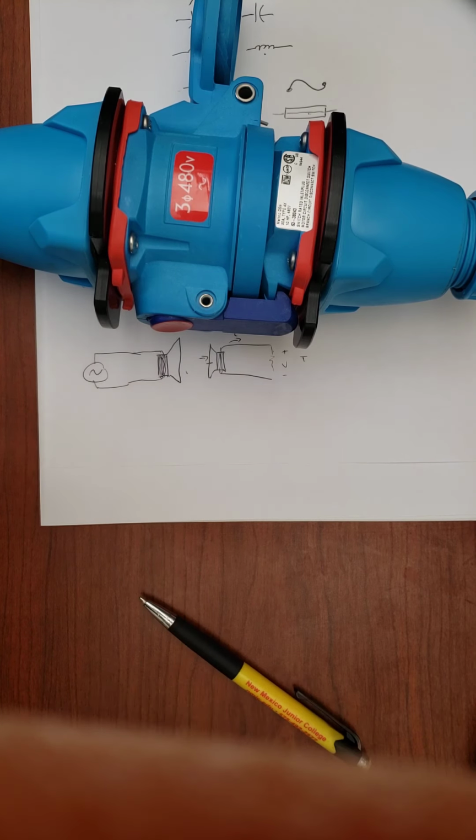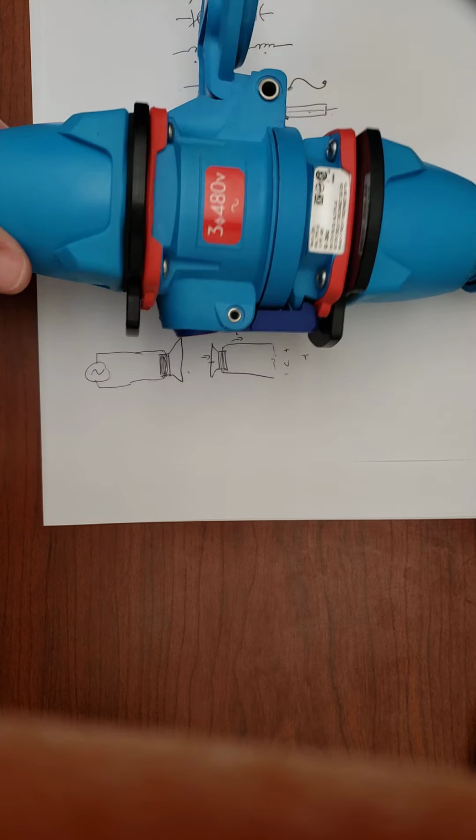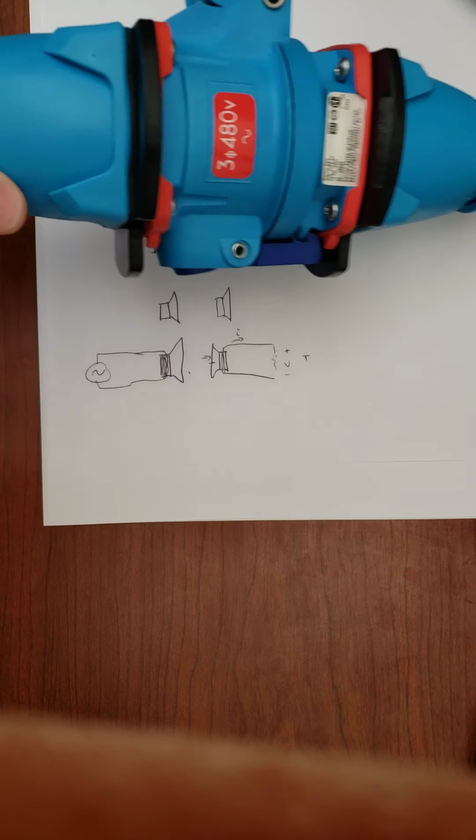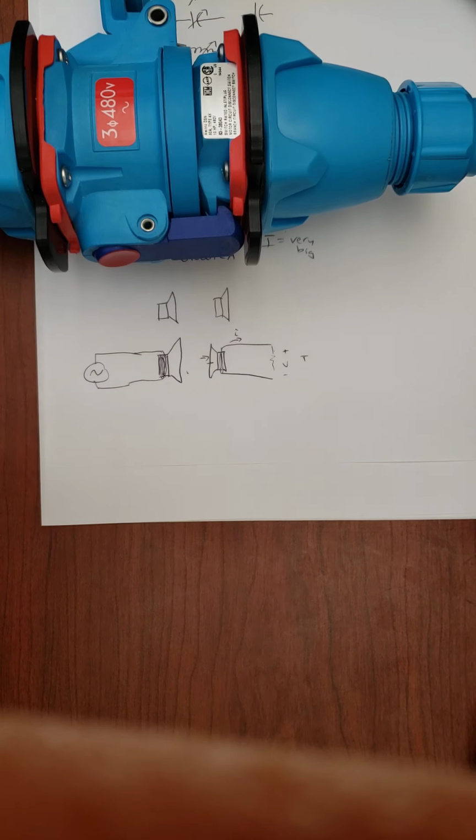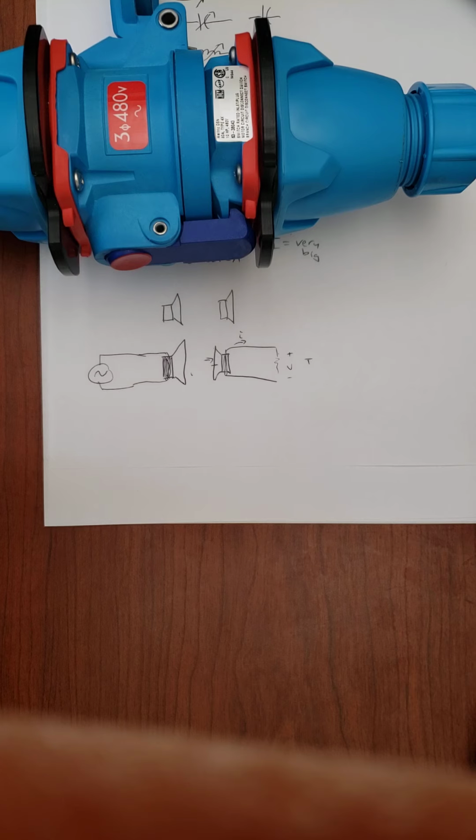And for your light switch in the house, it's probably not that big a deal. But if you start using higher voltage stuff like this 480 volt line, and in industrial settings where you might go to 11,000 volts or something like that, that little spark starts to be a bigger and bigger deal. And so there's whole training courses on how to deal with this. It's called arc flash. In your house, if you trip a breaker, you can just walk over to it. You just check to make sure it's safe, make sure somebody's not being electrocuted or whatever. But you can go press the breaker and have it reset.